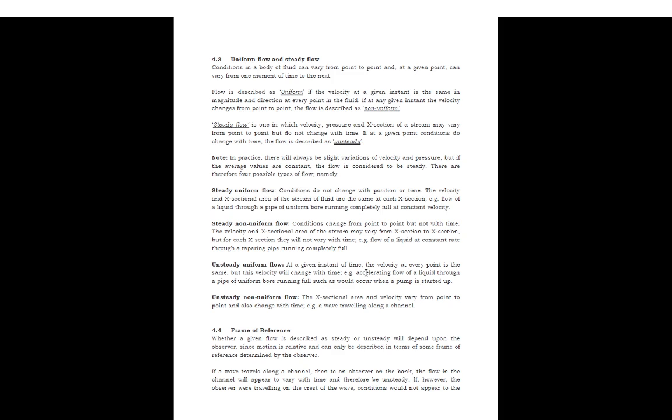This kind of flow takes place when the pipe is of a uniform bore and water is running at constant velocity throughout the pipe. So assuming the pipe is all circular, and the velocity in the pipe is the same, then we shall have steady uniform flow.